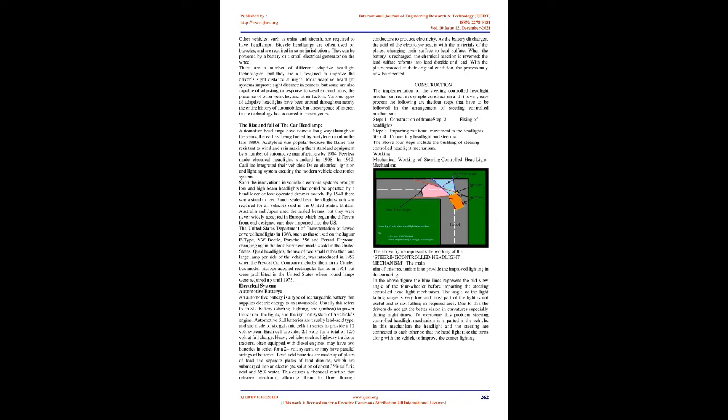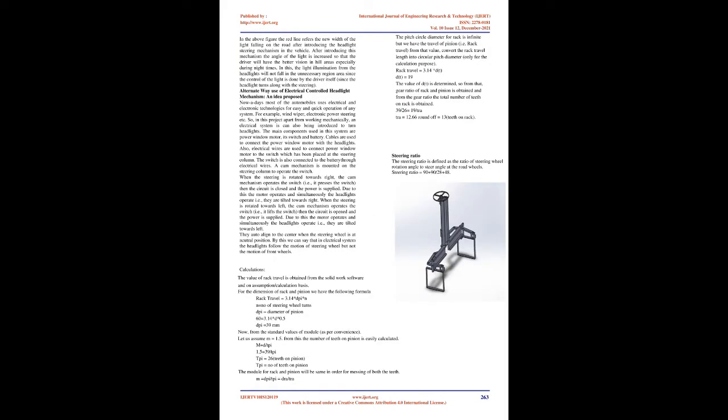Rack and pinion steering gear. The system consists of a pinion attached to the steering shaft, which meshes with the flat rack on the drag link. The pinion imparts left or right motion to the rack, which causes the tie rods to move the road wheels accordingly. This mechanism is usually adopted universally in all the cars available today with some major improvements.